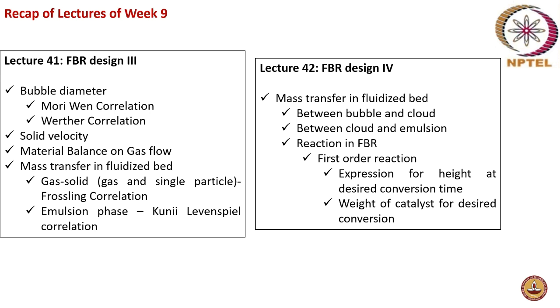So how to estimate the solid velocity for the fluidized bed reactor was discussed. Then material balance on gas flow and mass transfer in fluidized bed. There is a gas solid contact, right? So what is the mass transfer coefficient in the case of a gas and single particle was discussed. It was based on a Frössling correlation, and then mass transfer in emulsion phase.